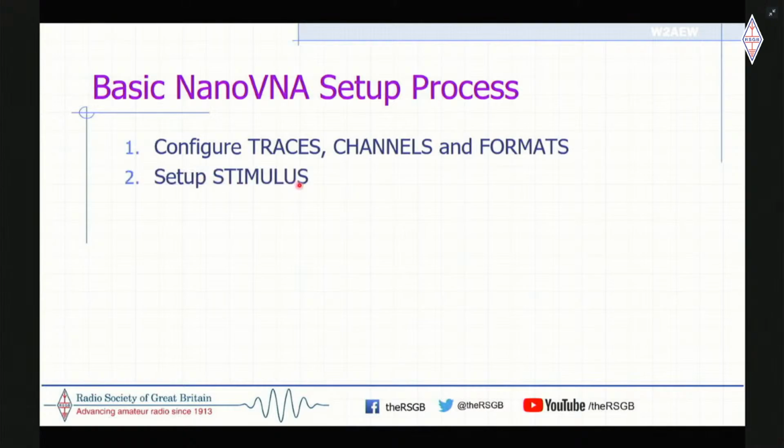Then I also want to set up the stimulus. What frequency range do I want to measure over? Start and stop or center and span? The order in which you do those things really doesn't matter. You can do one or the other. You don't really have to start one way or the other. But once you've done those things, then you're typically going to run a calibration and save it. If you've already performed a calibration, the calibration also saves these things as well.